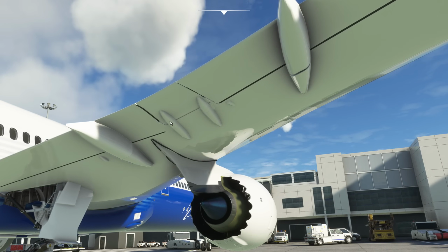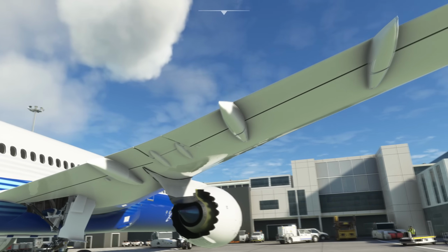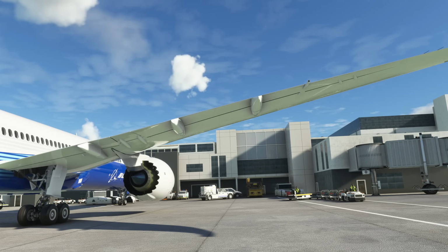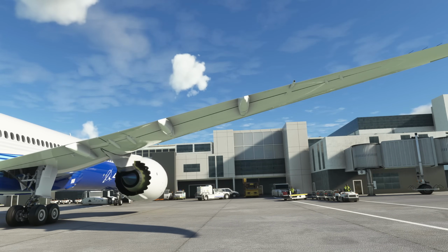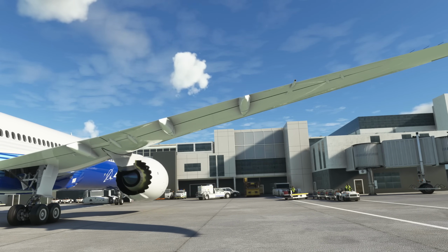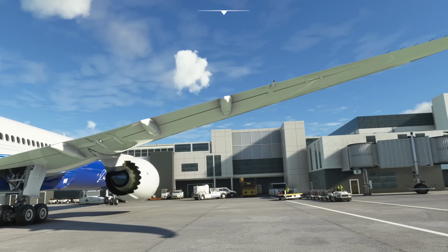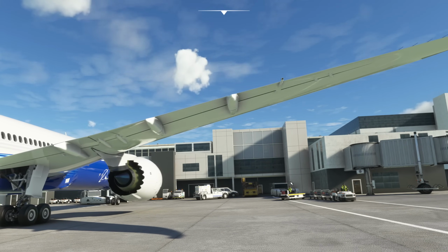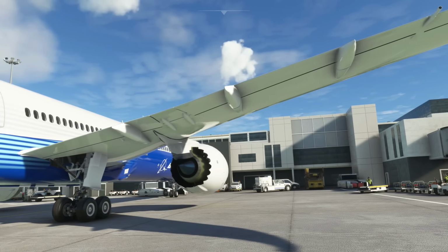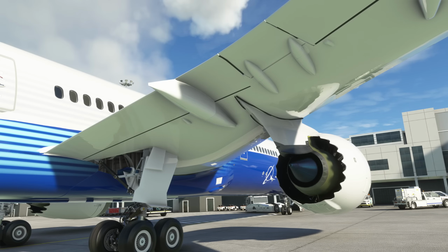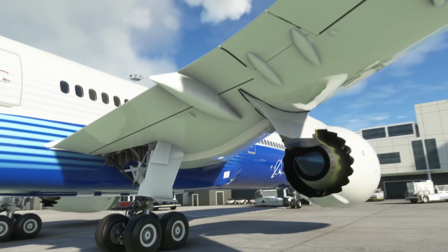The aircraft systems can also use all these controls to bring the aircraft into the best position for landing and takeoff. It can also use them to counteract turbulence. Very effective turbulence counteraction system. And if you're ever on a 787 in flight with turbulence and you look out at the wing, you'll see these things all moving around, sorting out the turbulence. It's very, very clever. They'll move together and against each other and all sorts. An interesting thing about the 787 as well is even the flaps might adjust in the cruise, not as part of the pilot's instructions, but as part of the aircraft's efficiency, setting up the wing just how it wants to be for that phase of flight.